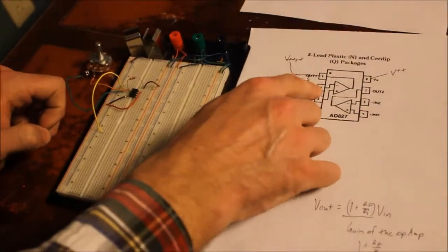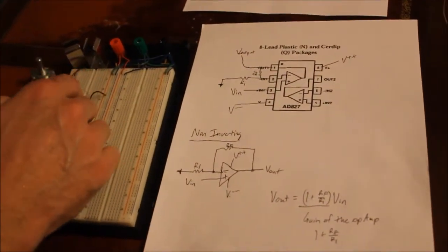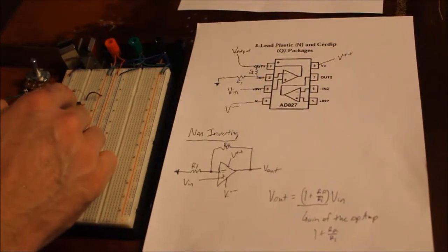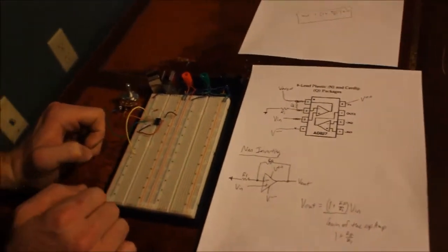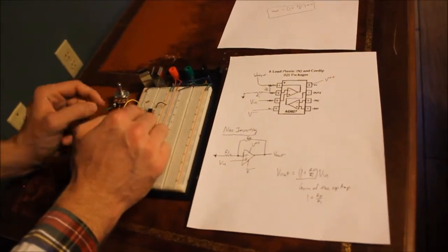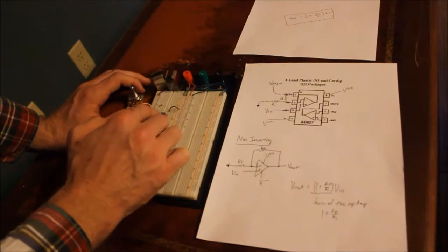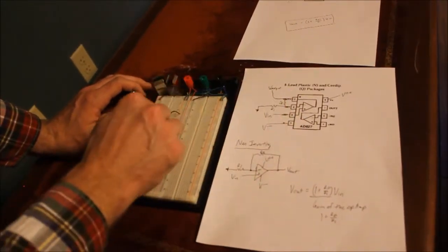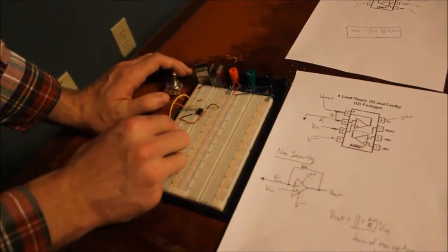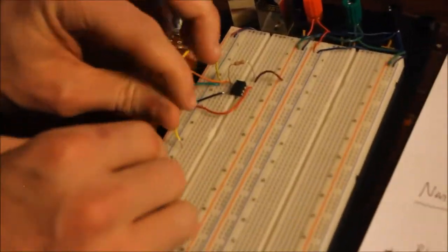Into the inverting side, green is ground, so we've connected from ground to our input resistance, which is 2.2 kilo ohms. We've connected that to pin 2, and also in parallel with pin 2 and this top pin right here, which is the output voltage, in fact, we've drawn a line from right here, this yellow line.